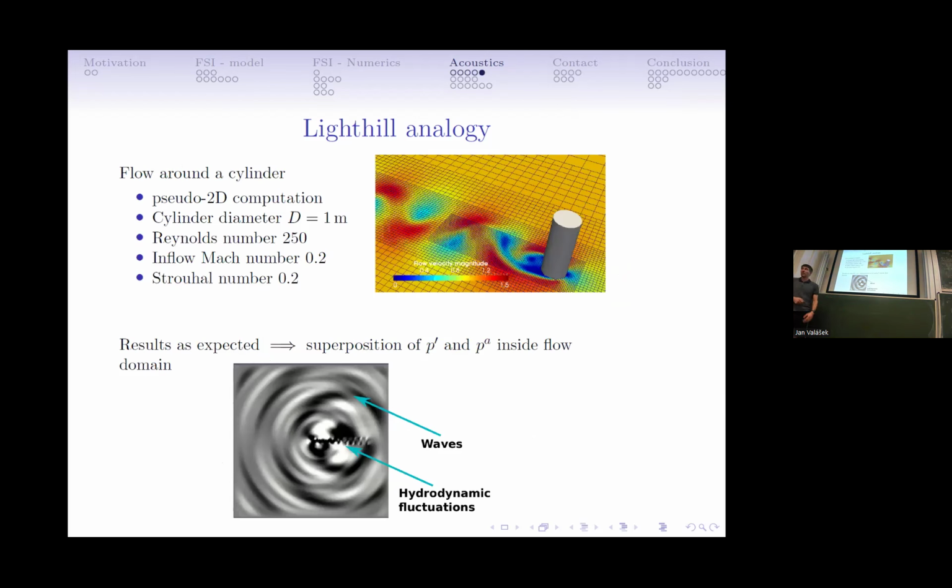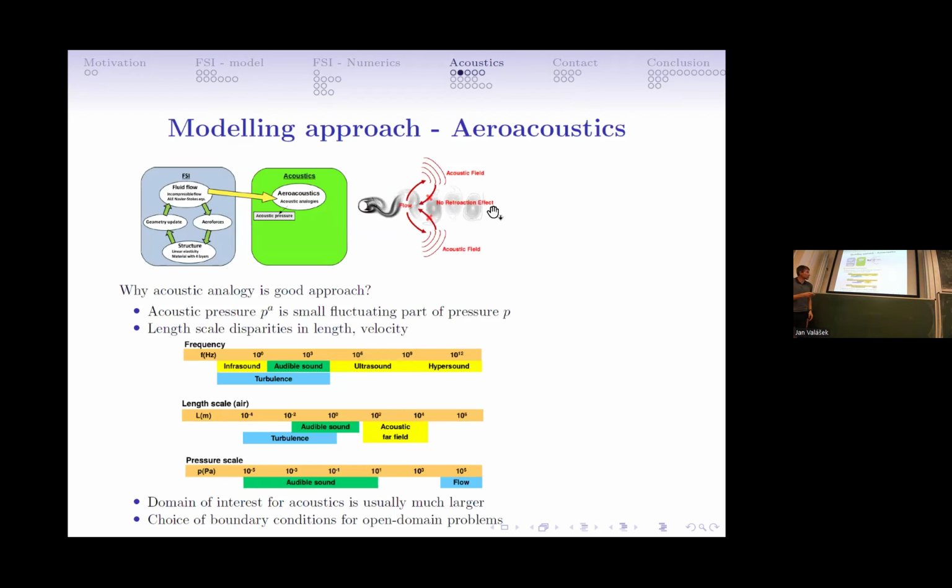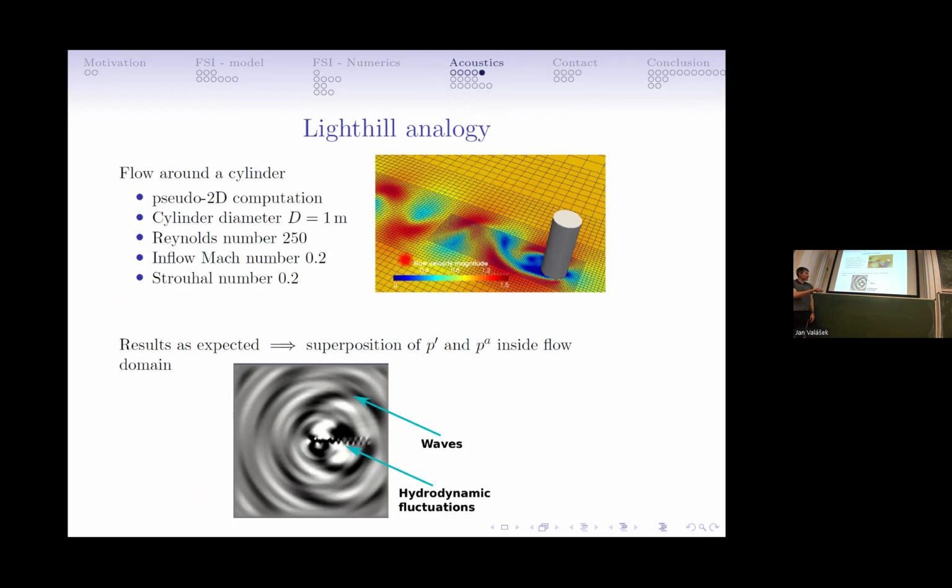Okay, so here is a very simple sketch taken from the book of Professor Kaltenbacher, where he first simulated von Karman's vortex street behind this cylinder, as you can see here, these typical vortices of flow. And when he applied the Lighthill analogy on this fluid flow, he computed the sound source based on this velocity approximation, and then he gets such a picture.